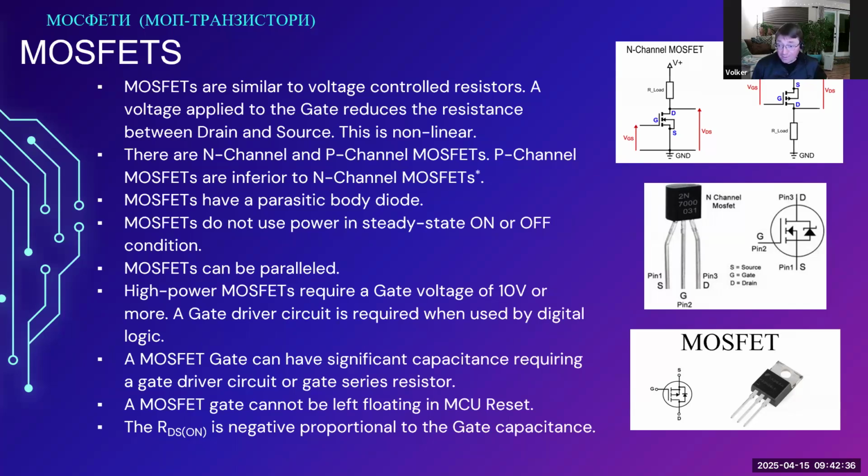However, they very quickly go into the hundreds of picofarads, which is beyond what a microcontroller pin or a logic pin is rated for. They can, for power MOSFETs, go into 4 nanofarads to 10 nanofarads for the really high power MOSFETs, which can still be cheap devices if you pick the right one.